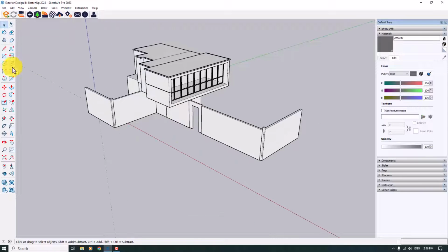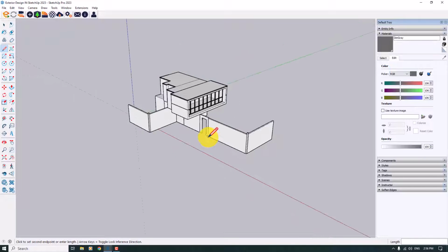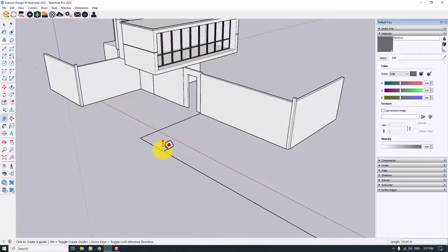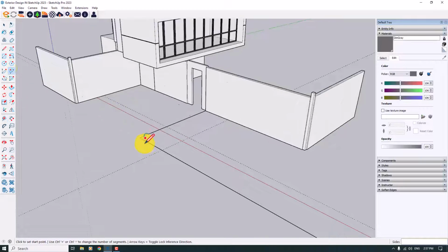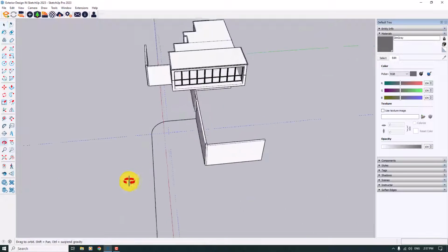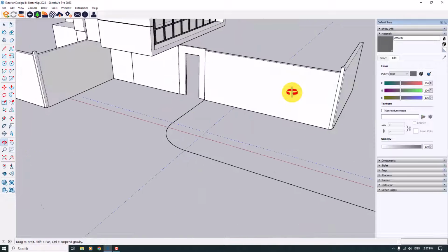For doing this, I only need to click on the Line option here and draw an asphalt road from here about 6 centimeter, and another one about, for example, 19 centimeter. I will pick up the Tape Measure and tape it about 2.2, and from this line 2.2 again. Click on the 2-Point Arc and create your main fillet like this. Delete your tape measure guide lines.